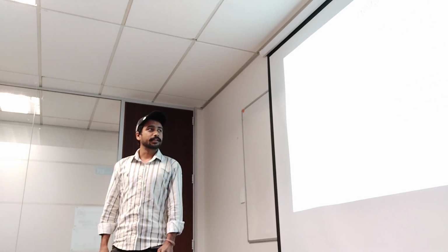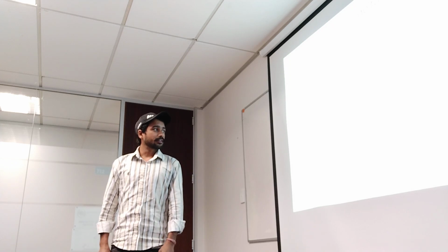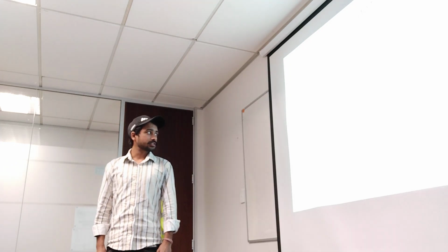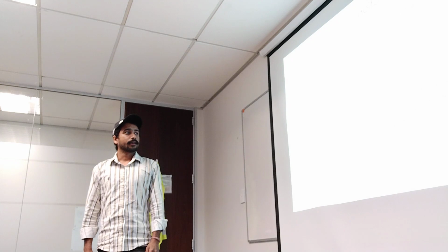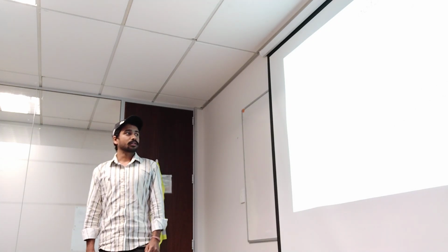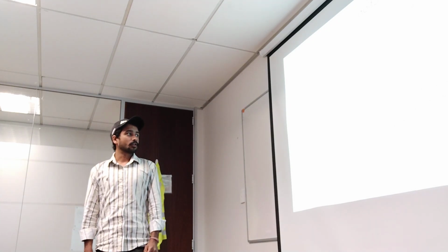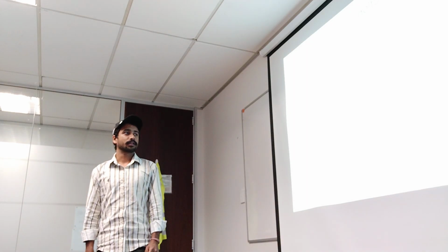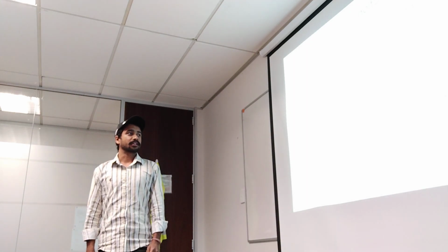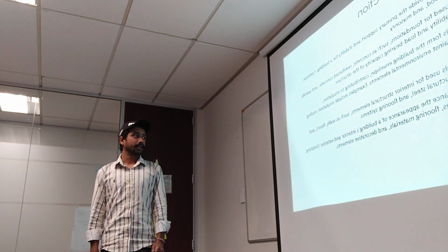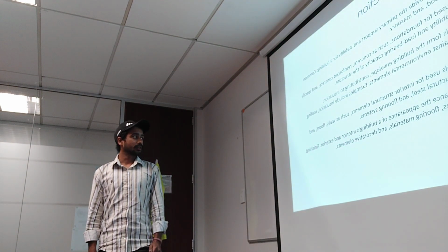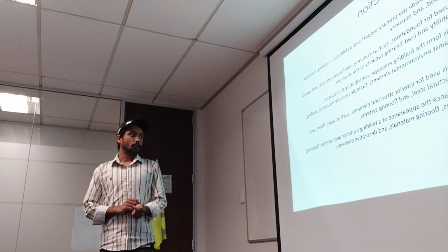And the fourth one is interior structural material. Materials used for interior structural elements such as walls, floors and ceilings. Examples include drywall, structural steel and flooring systems. And the fifth one is finishing materials. Materials that enhance the appearance of a building's interior and exterior. Finishing materials include paint, wallpaper, tiles, flooring material and decorative elements.